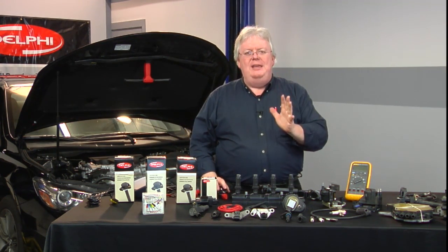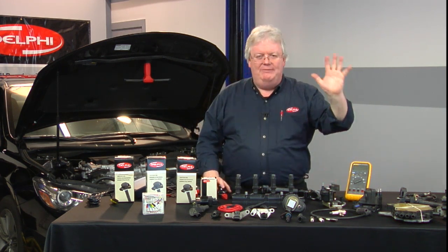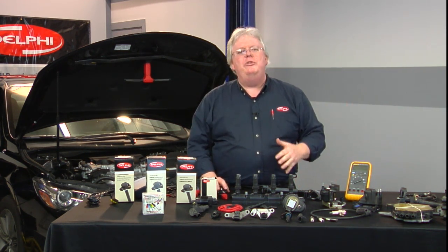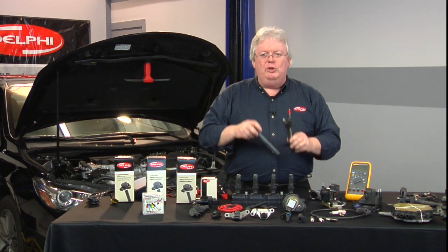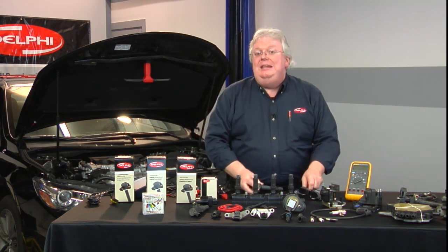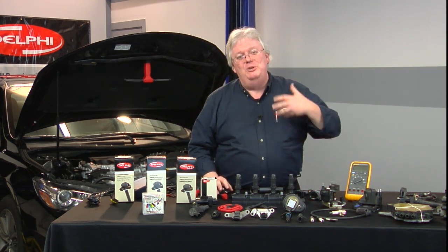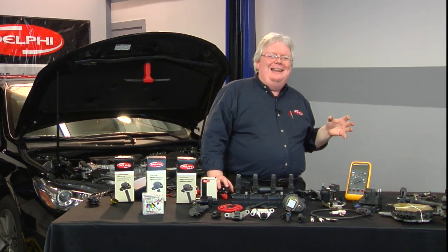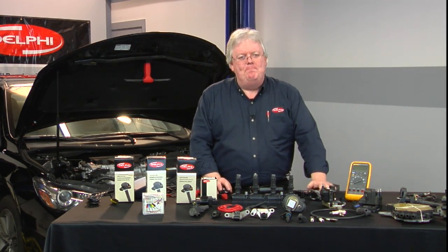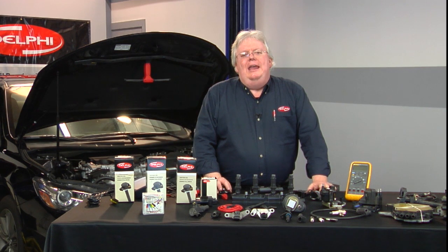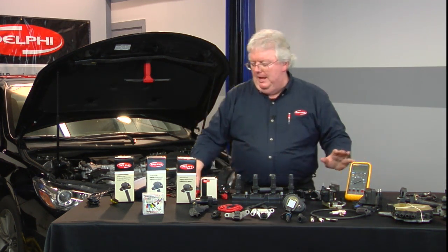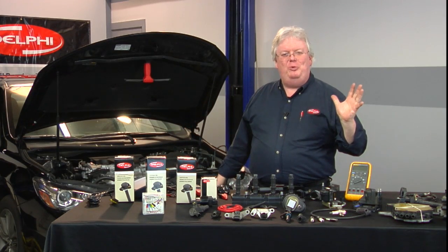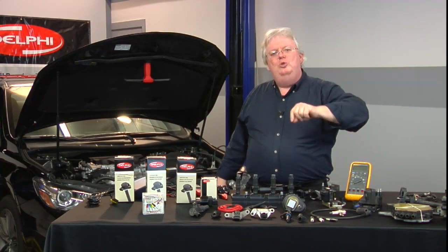So the same thing that's been happening with DIS, even the older systems, is occurring with the coil-on-plugs, and because they're a little smaller, a little lighter weight, they tend to be a little bit more prone to this. That's why you're putting more on than you used to with a single coil mounted somewhere in a lesser hot spot of an area. Now let's go to the car and look at what we can do with a meter, an amp clamp, and a scope. So whatever your tools of choice are, on a Ford 2-wire coil.